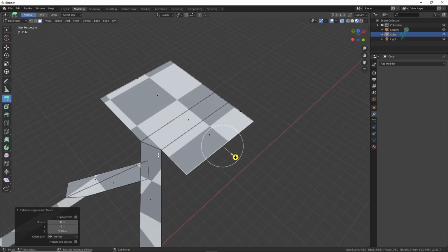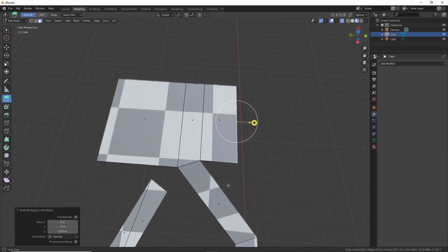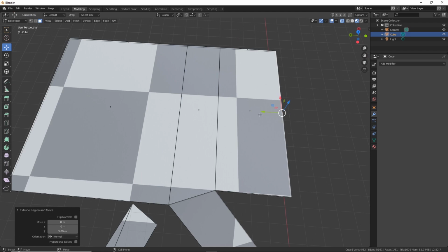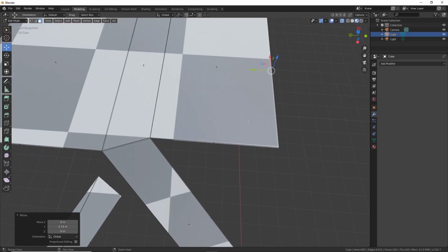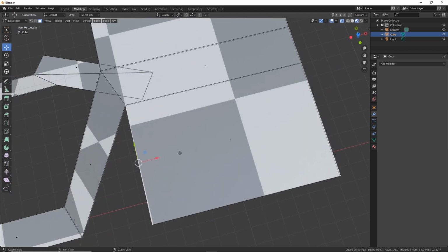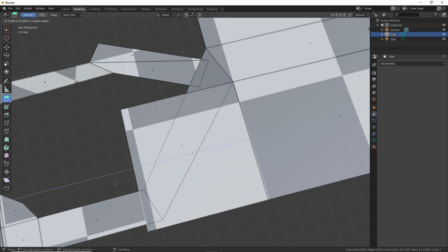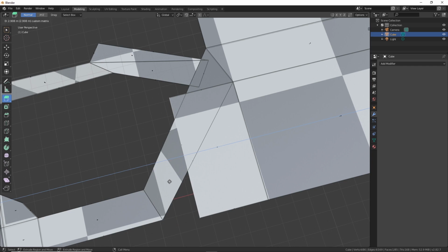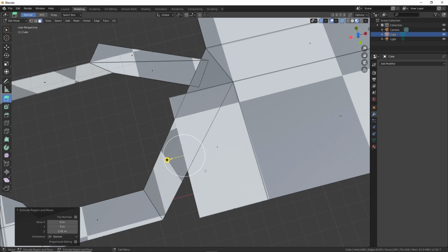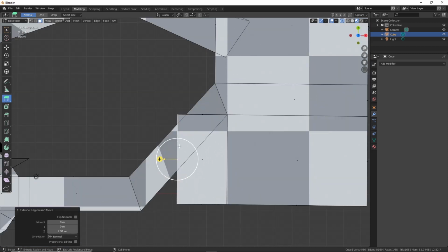And then for that matter, I could even make this like a hole. We'll make this a bigger one. And then extrude. So what I'll do is I'll line these points up from the top. Show you how this works. W or F3.